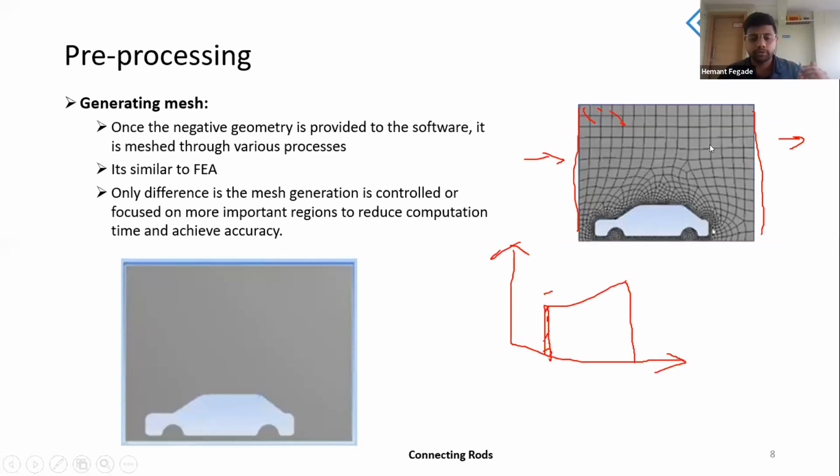The other region is defined because of certain constraints of the physics, so that we will have a certain space of simulation, because until and unless we have that domain size defined, we won't get accurate solutions. So it's a concept involving upstream flows and downstream flows as well, considering the fluid flows. Essentially we need to get the fluid at a steady state when it's moving over something. So all of those parameters considered, we have the upstream and downstream, and the domain size constraint.